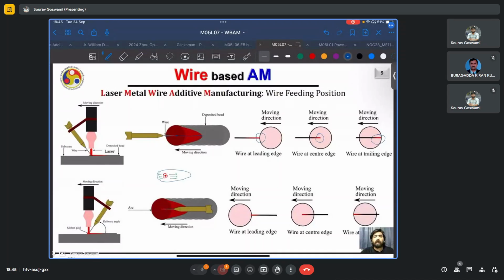And for best results, we want the wire to melt near the surface, near the center of the melt pool, as that is the hottest region and that has the least, say, surface movement of the fluid. Of course, there is internal convection, and the melt pool also tends to be deepest right under the laser beam.